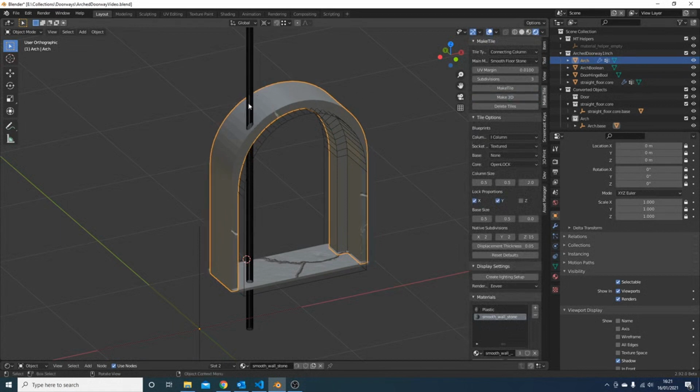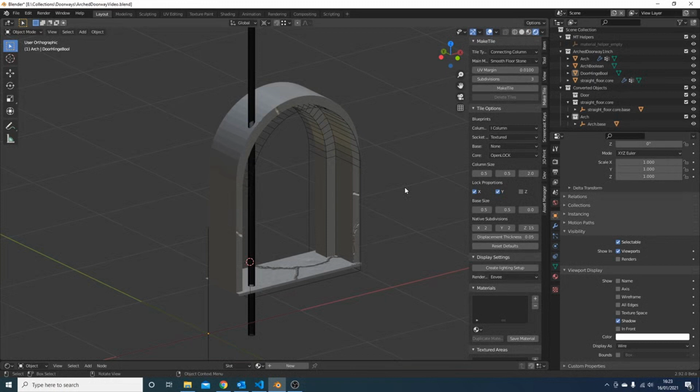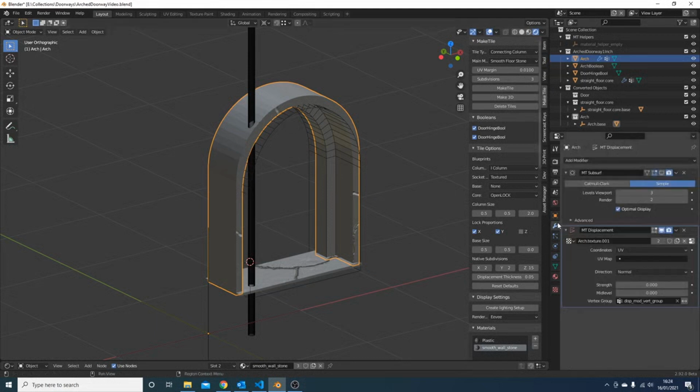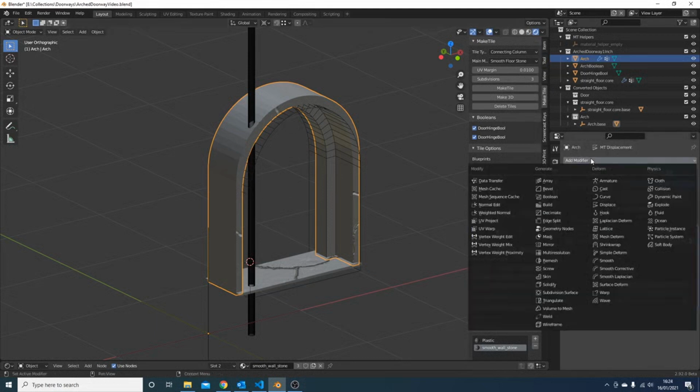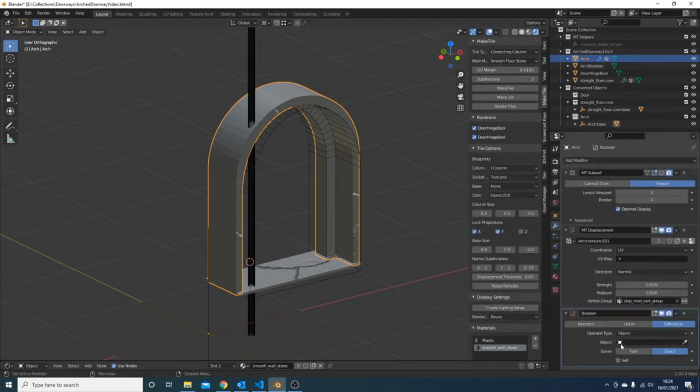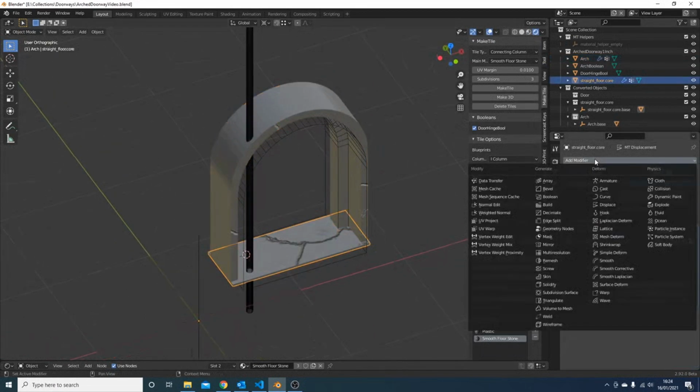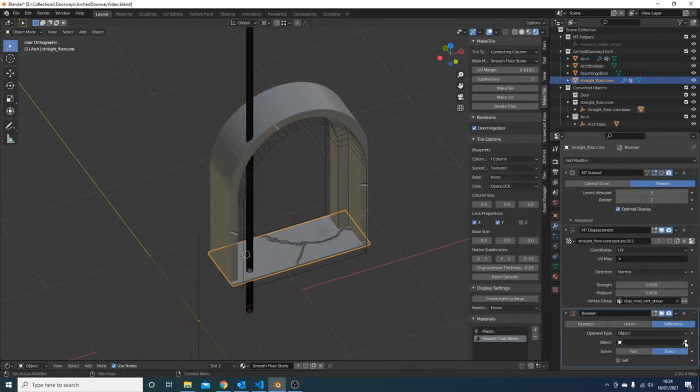Excellent. Right. Okay, so there's a couple of things I still need to do to set this up. First of all, I want to have a hinge. I want this boolean to cut through the door frame and the floor bit. So I'm just going to manually add a boolean modifier to these two. I'm going to add modifier boolean and difference. I'm going to use the fast solver because the new exact solver is really slow, and add modifier boolean.